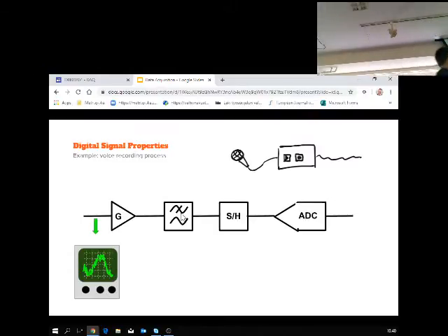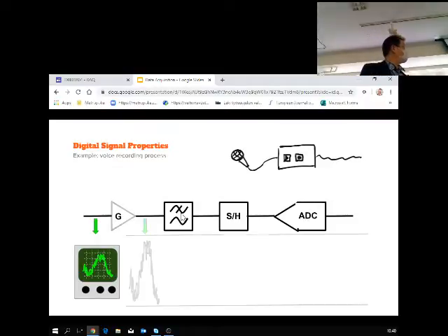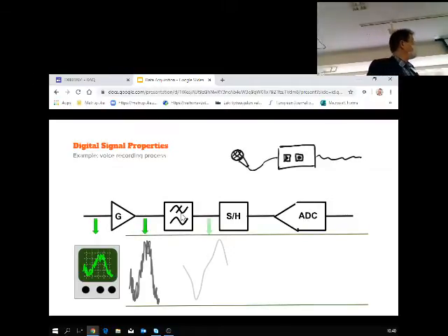So you need some amplification before the A to D converter, but also some cleaning up. There's usually some spurious noise on your signal, and you need to clean it before getting further.